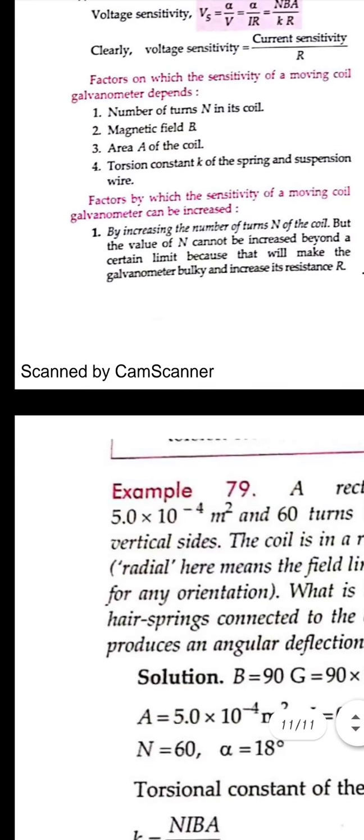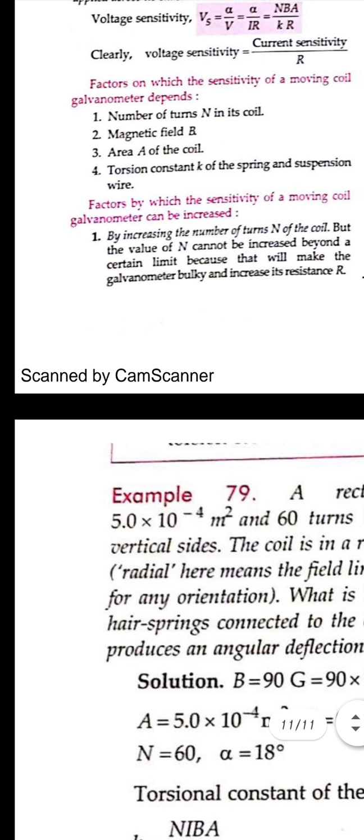So the galvanometer is a device which measures small currents with the help of a linear scale and a pointer. This pointer moves due to torque. Why is there torque? Because the moving coil, a rectangular coil of copper wire, is suspended between two magnets, and these magnets produce a magnetic field which puts a torque, a couple of forces, on the rectangular coil, which allows it to move through an angle alpha.